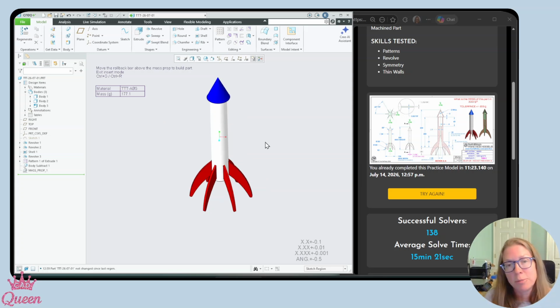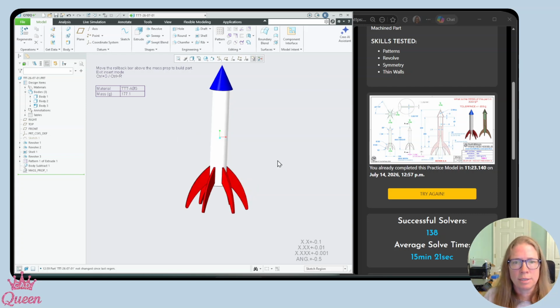So anyway, I hope you appreciated going through some of Creo quirks on this great challenge, looking at sketch regions for revolves, looking at some interesting arc geometry, extruding relative to a cylinder edge, and using some of those body options before applying those colors to this particular part.